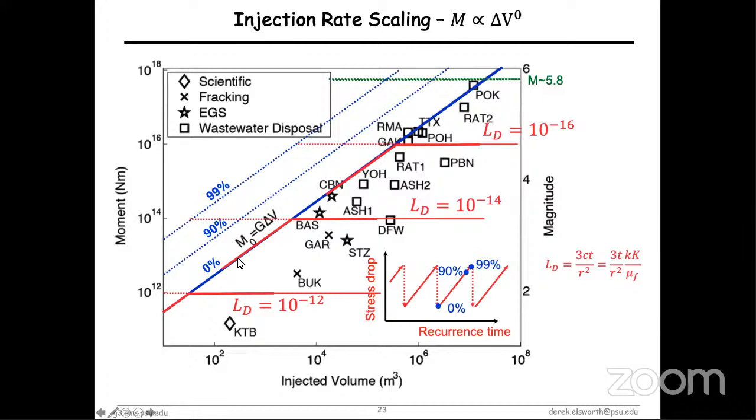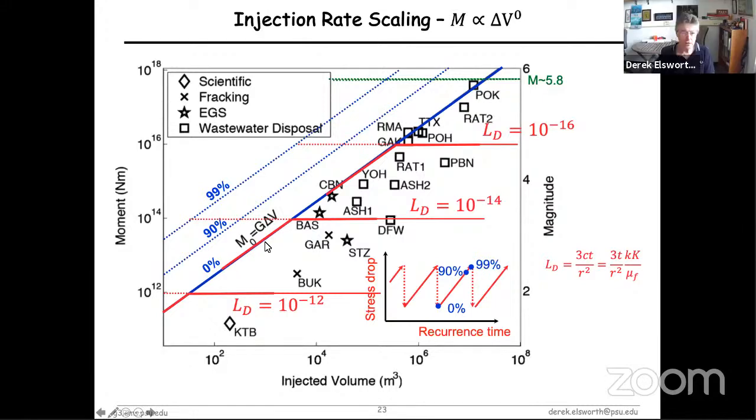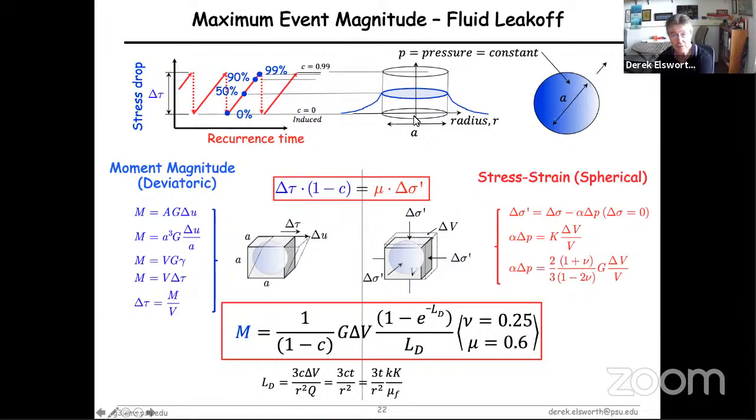And this initial one-to-one slope is the time where you are filling the bucket up. It starts off with zero pressure within the bucket, and it fills up this permeable fault all the way to its edges, but at a very low level. As you keep injecting fluid at some injection rate, this surface slowly increases up to some magnitude. It has a low permeability exterior and a very high permeability fault, and this low permeability exterior controls the leak-off rate.